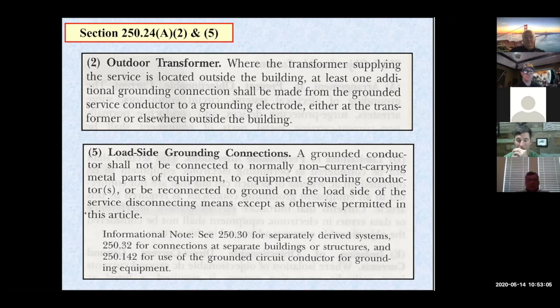You got to carry the ground. You cannot connect neutrals and grounds together anywhere except at the main panel. So as you go downstream, that grounding conductor is basically a separate system by itself. It's required and necessary, but you don't connect it to anything else, just to grounding all the way along.